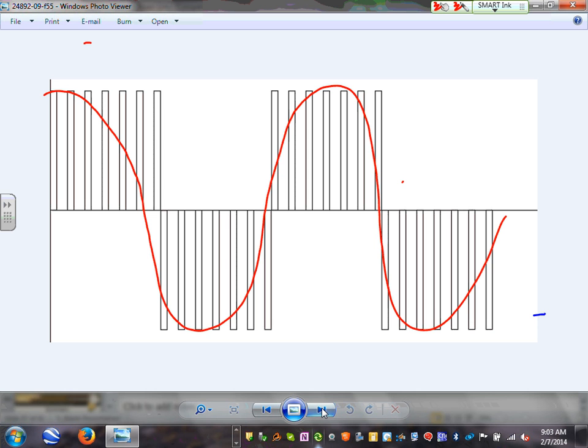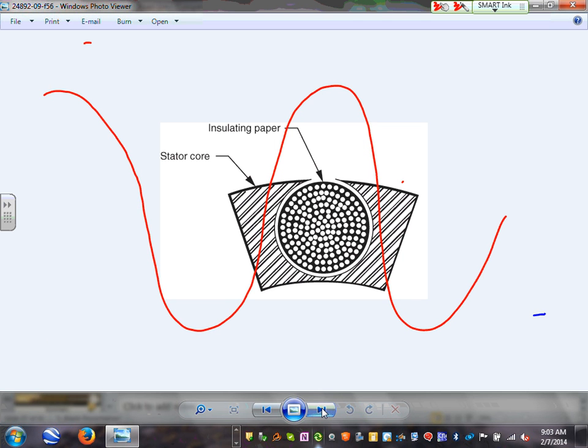So when you're driving your motor with a VFD, you're not actually putting in a sine wave, you're putting in pulsation. Pulse, pulse, pulse, pulse, pulse into the motor. And the motor is dumb enough not to know, and it keeps working. By changing the pulsation and the distance between these pulses, guys, you can control the speed of the motor. Don't you think that's smart? If you just reduce the voltage, you burn the motor. Instead they make pulses, and they reduce the distance between them, and the magnitude and the frequency. They can control the frequency and make the motor run much better.